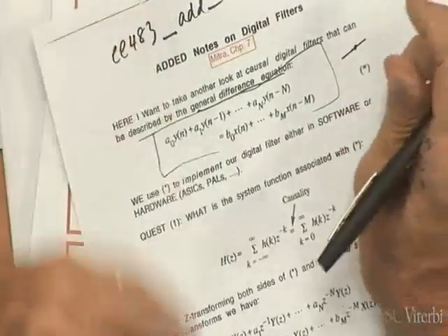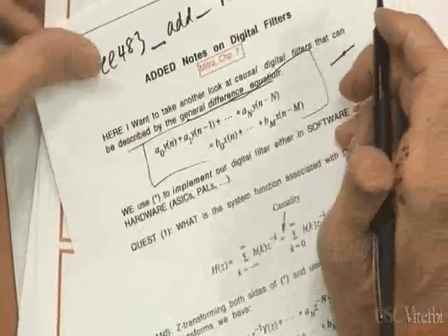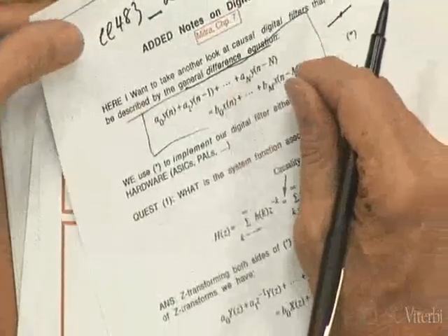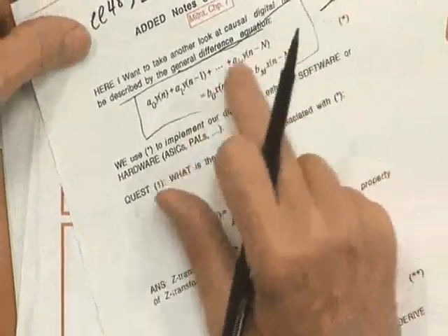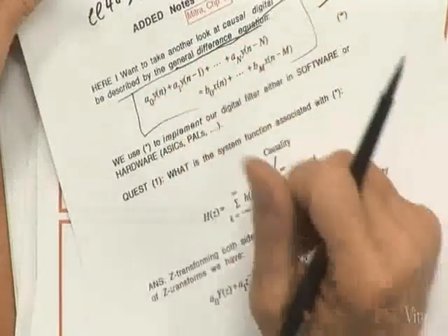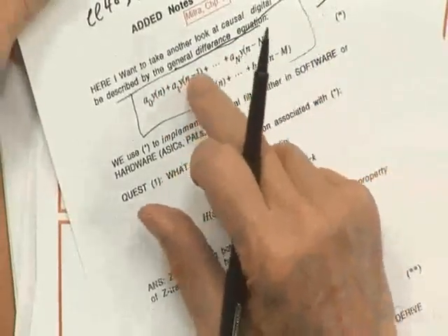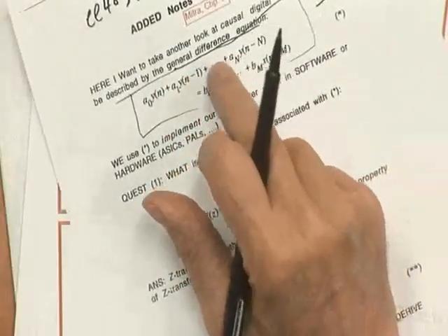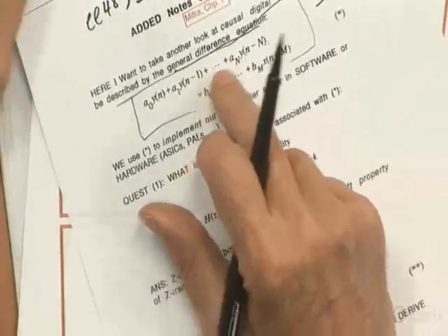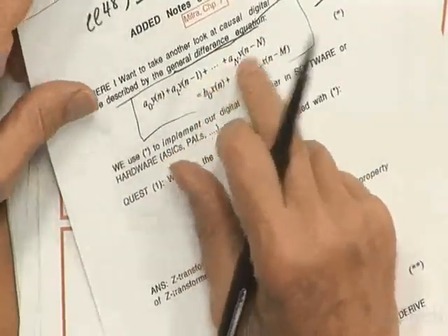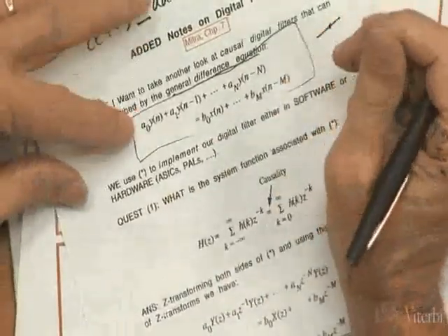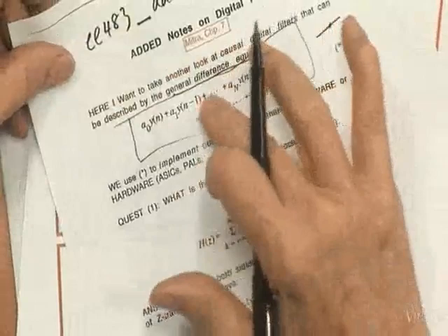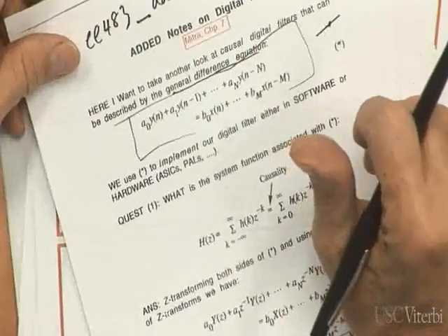See, this is what you use, the time domain representation. You generate this using the FPGA, the multiplies or adds. You do have to register certain values because there are delays, and then there are also multiplies. Typically, for a pipeline, you register the values after the multiplies, etc. But this is what you use to implement the digital filter. You use the time domain representation of the difference equation.